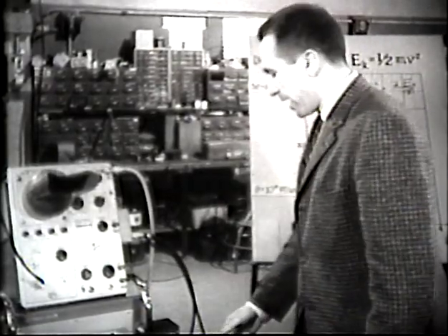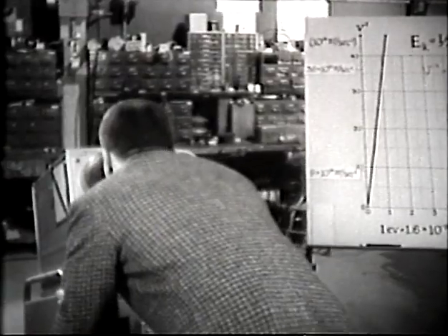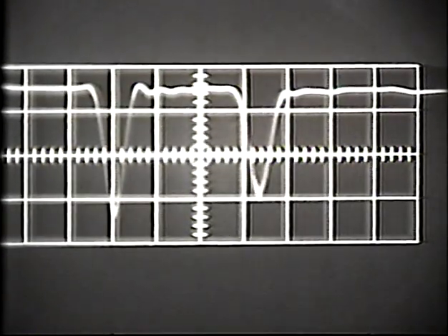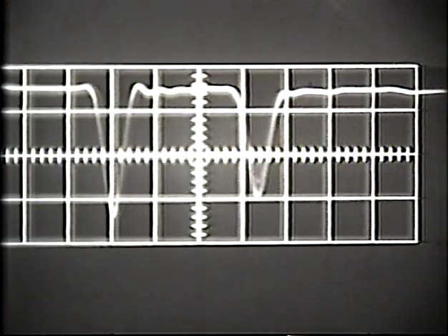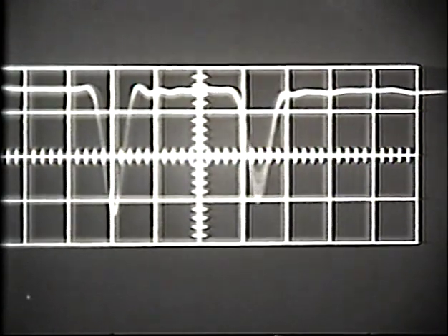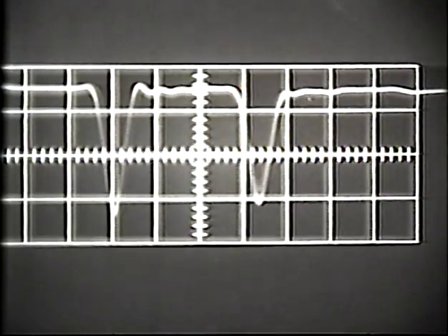The connection is complete now. I'll turn the beam on again. Turn up the gain to see better. There are now two signals on the scope. As before, the left-hand signal is produced as the burst enters the pipe, and the new right-hand signal is produced when the burst is stopped by the disc at the end of its 8.4 meter flight.